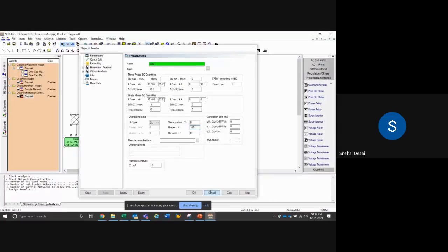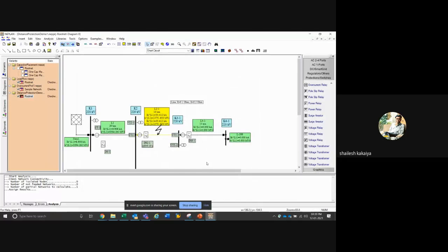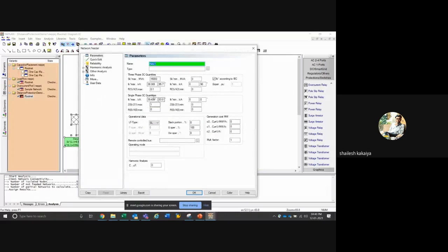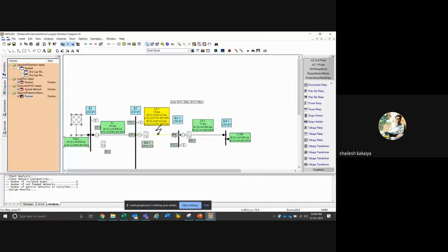Yeah, and I was looking at particular modules of that. There's no specified module as such, because from phasor data concentrators, what is the data we are expecting? The state of that particular bus, voltage and phase angle. Yes, fine, that is what I wanted. So that data is fed into this particular network feeder element, which is a grid equivalencing element. With that, we can check how our system is responding.